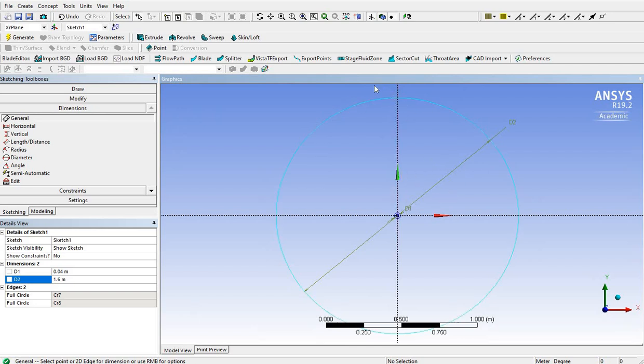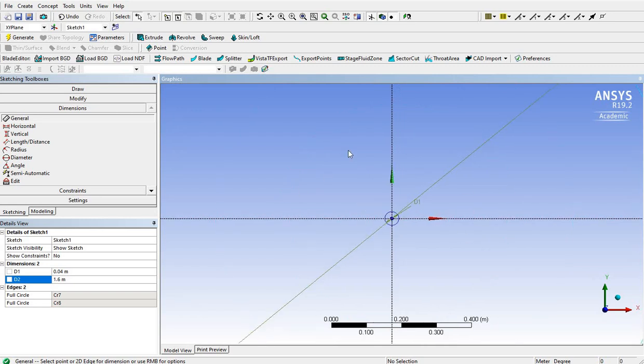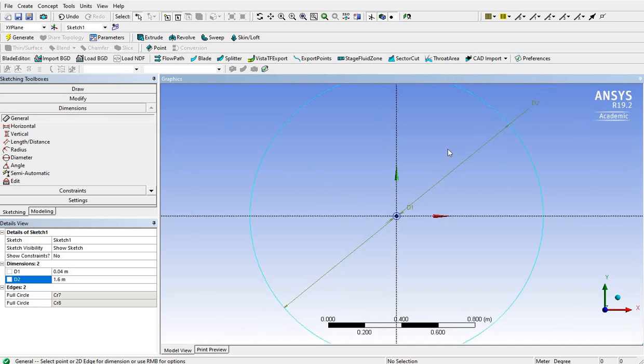Also, it's good practice to do two external domain sizes. So this is one size, make another one a little bit bigger, maybe 2 meter, okay, 2 meter diameter, and run the case again and see if the result around this object is changing or not. If it's not changing, then it's good enough. The external domain size is good enough. Okay.